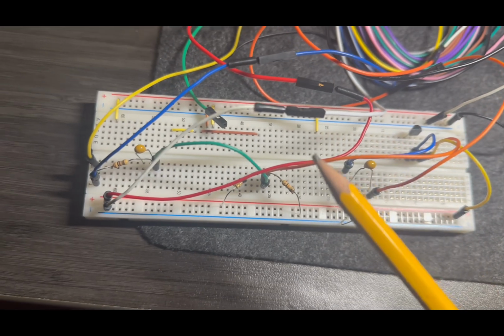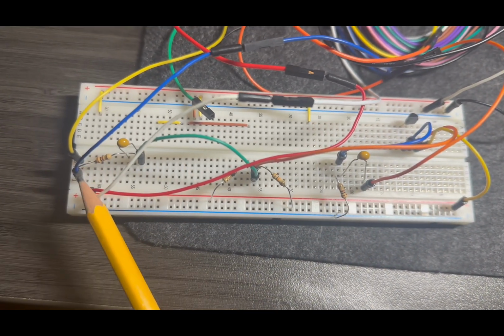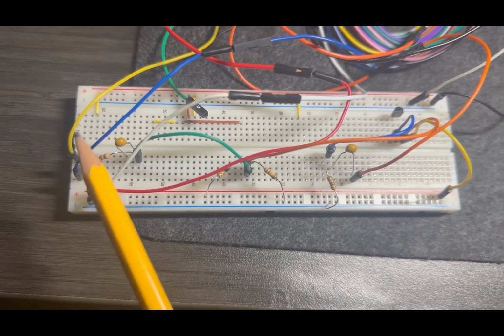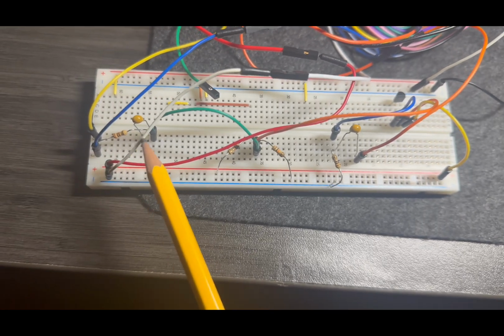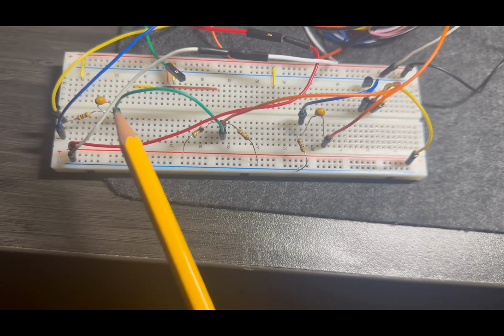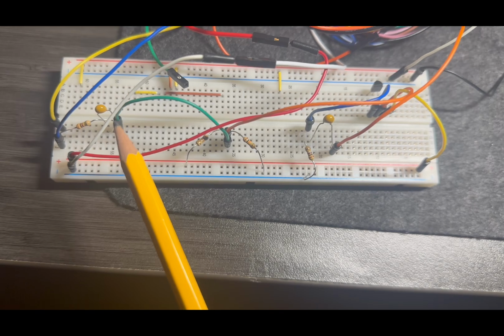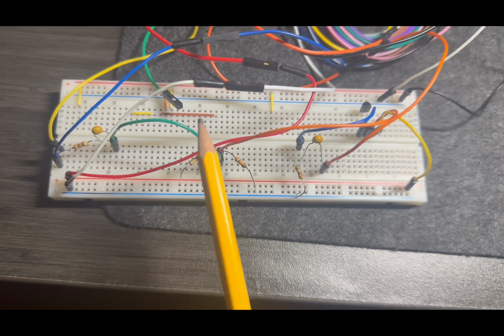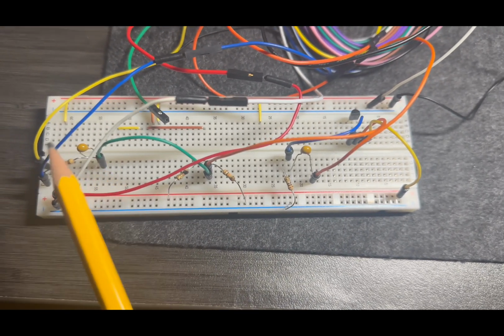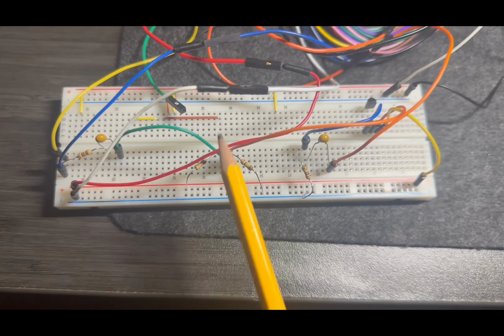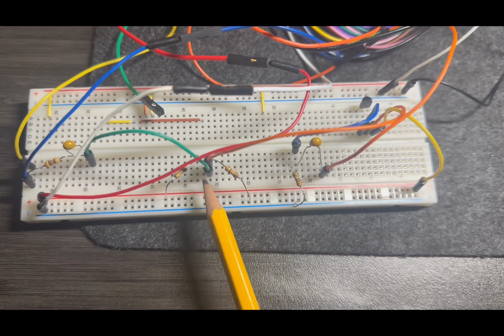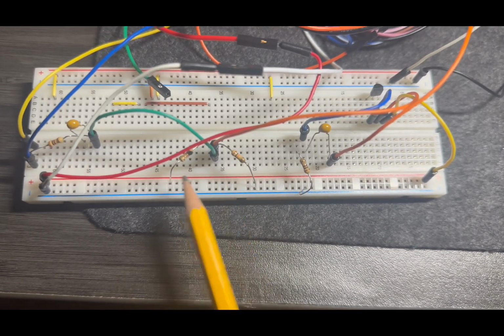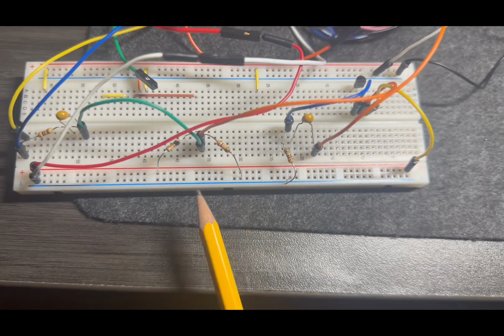Now, in addition to that, the input voltage over here goes through our 100 ohm resistor. It then goes through the capacitor, which pretty much just prevents DC from going back through and allows the AC to then change the voltage right here at the center that is shared between these two resistors.